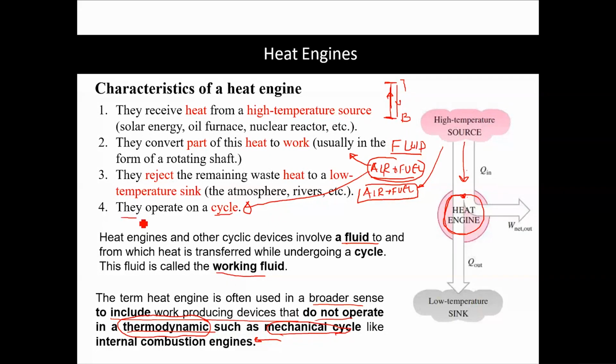Here, the fourth characteristic is not mentioned, that the fluid should operate on a cycle, or move in a cyclic manner. The engines operate in a cyclic manner even if the fluid within the engine is not undergoing a cycle, as in the case of internal combustion engines. You would still have the heat engine. It's a very broad term which incorporates both the fluid undergoing a cycle, or otherwise there is a mechanical cycle associated with it. There has to be a cyclic process that takes place. It is not necessary that it is a thermodynamic cycle.